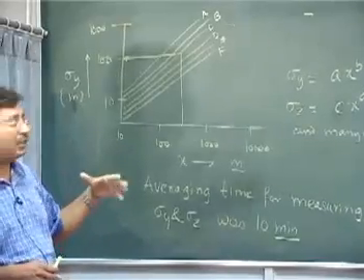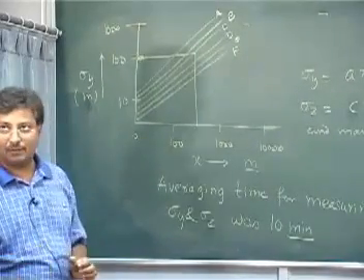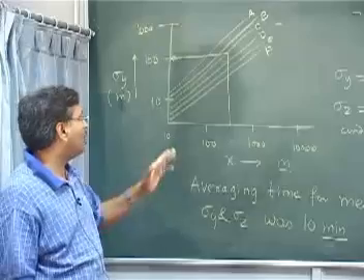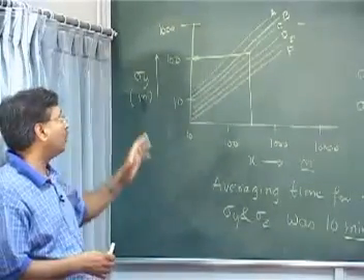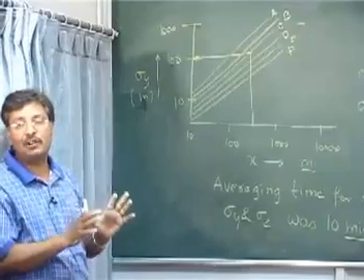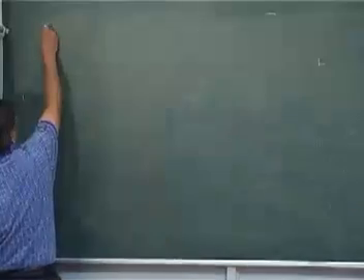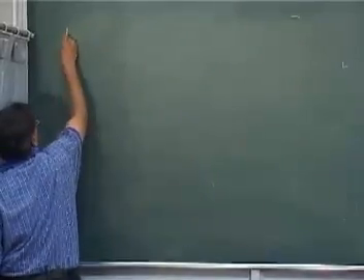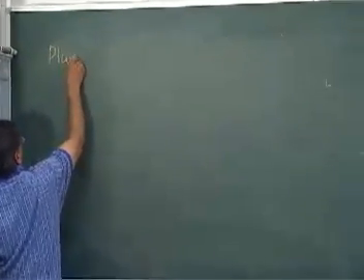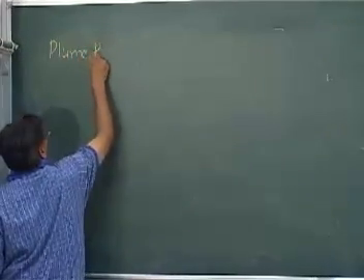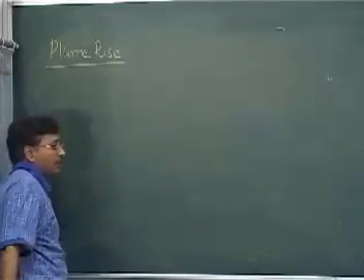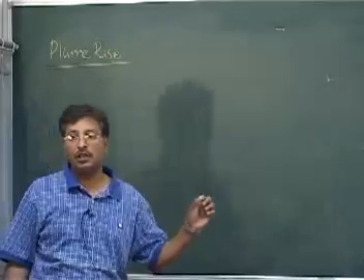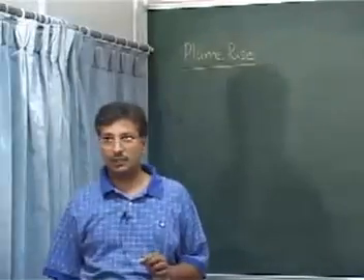There are many other formulas that I will probably put on a slide next time to show you how sigma y and sigma z can be calculated without using these graphs. So graphs were fundamental. The other thing you need to know, before you are set to use that equation, is the plume rise.